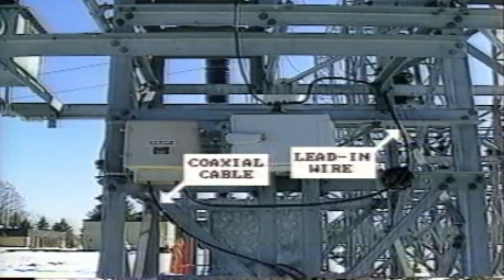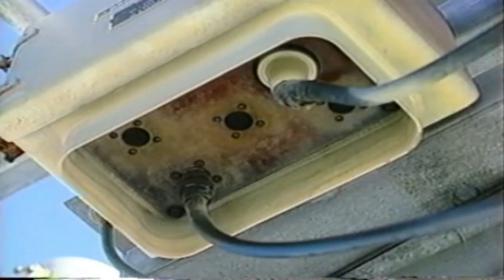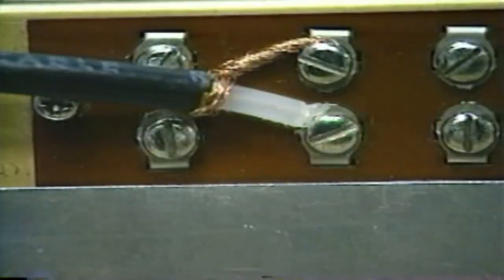In many companies, this is checked annually as a routine because coaxial cable is much more fragile than most other cables. Sharp bends, nicks, and crushing of the jacket can easily degrade its performance. The connection of the cable to the LMU is sometimes a problem. If a coaxial connector has been used, make sure the connection between the braid shield and the body of the connector is solid. If the connection is hardwired, check for high impedance paths to ground and burn marks between the center and the shield of the coaxial cable.